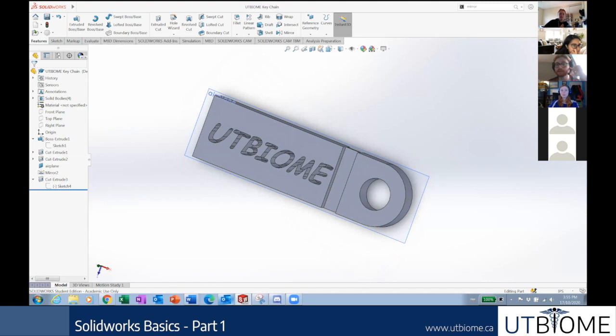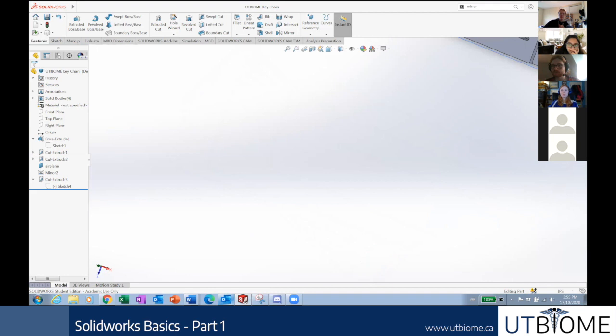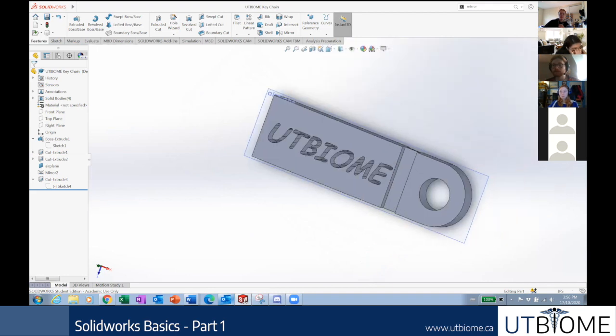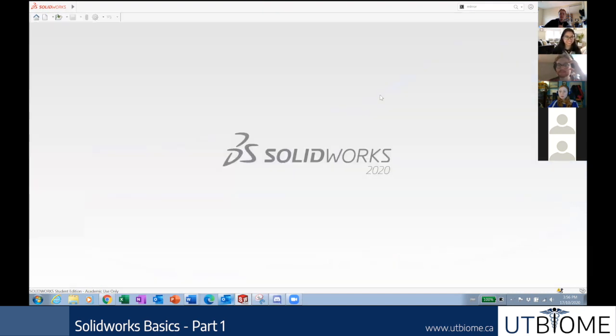If you click this big X all the way at the top right of your screen, this closes all of SolidWorks. If you do the one that is slightly lower, within the screen that your model is in, in an area where I can literally move my model, then that just means you're only closing this part. So I'm going to click that small X, not the one at the top right, but the one that's slightly lower. I click that, and SolidWorks is going to stay open.